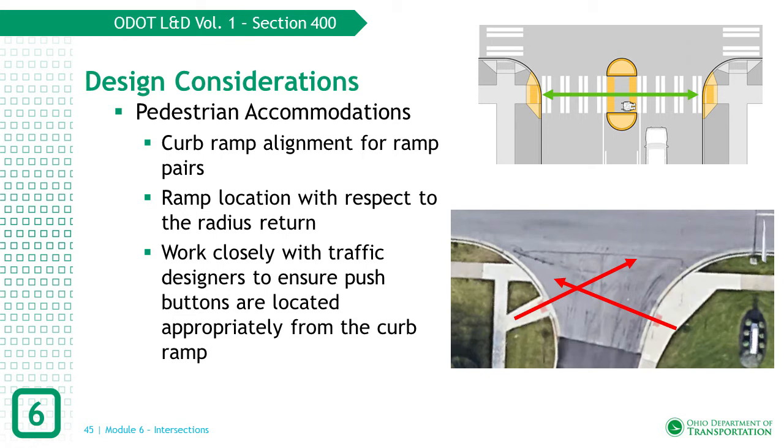The ramp alignment and location should be carefully reviewed to identify an optimal crossing location. Location of pedestrian push-button facilities can also influence curb ramp locations. There are specific design requirements that must be met for ADA compliance. It is important to work closely with traffic designers to coordinate the location of the curb ramp relative to pedestrian push buttons.